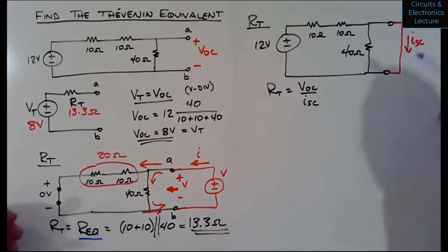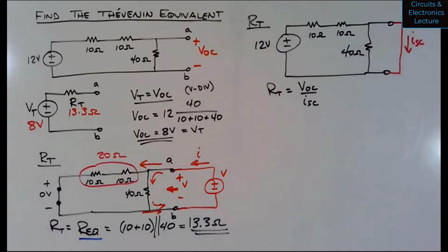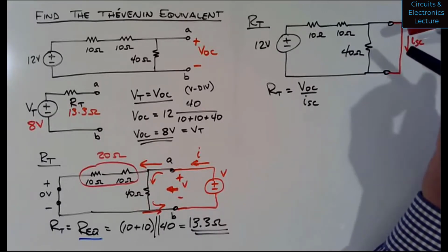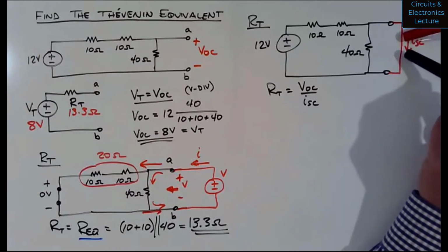Let me figure out the voltage across that 40 ohm resistor. See what's going on here. Remember, if I take two probes of my voltmeter and touch them to the same node, you would see 0 volts. In fact, I encourage you to try this during lab.